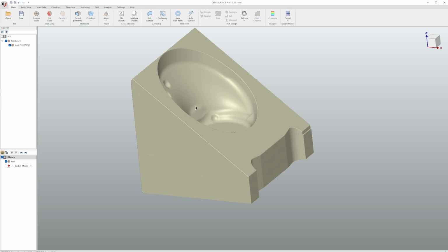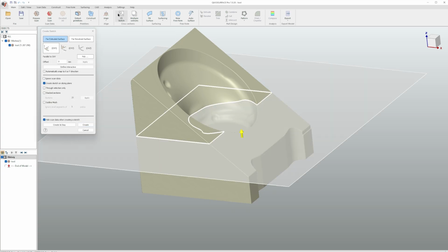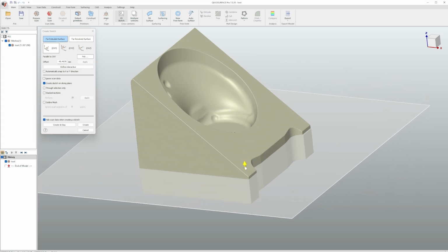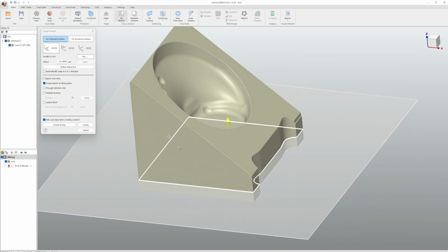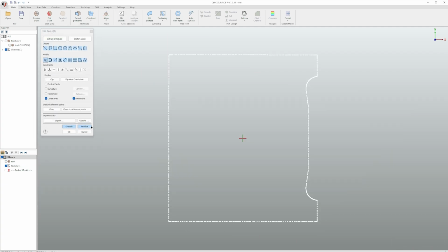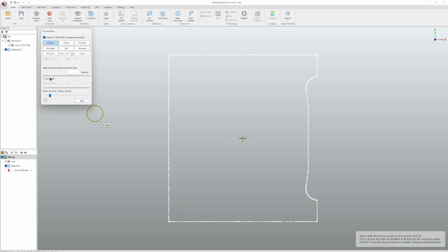To begin to make the main body, go to 2D sketch and drag it down until we reach a place which we can draw off. Once you're happy with it, click create. From here, click extract primitives and make sure the auto fillet is turned off.